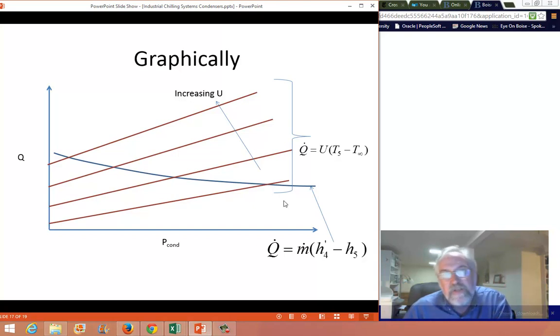and a lower effective heat transfer coefficient because of the way the temperature affects the transfer coefficient. If we want to go back to that original condensing pressure under that higher outside condition, you have to increase the U again by maybe running more air through it, turning the fans on higher, and that brings you back to a new equilibrium position. So there's a trade-off here between what the compressor is doing and what you have to do in the condenser to make it all work together.